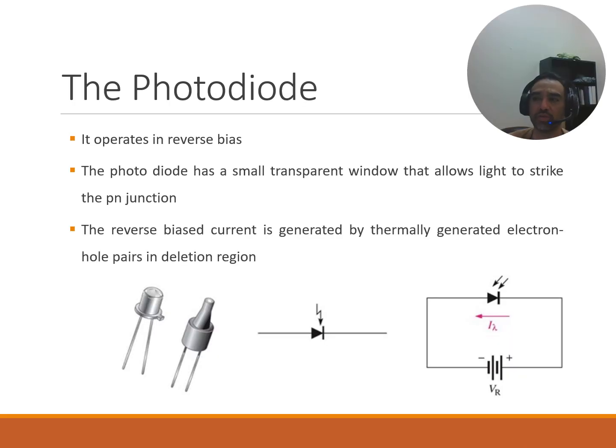The next one is a photodiode, right? So you might think that sounds familiar or similar to an LED. Nah, different things. A photodiode operates in reverse bias. And so it works when electricity, again, is going in the wrong way compared to a rectifier diode. And even though electricity doesn't like to flow like usual, the diode can still work by detecting light.